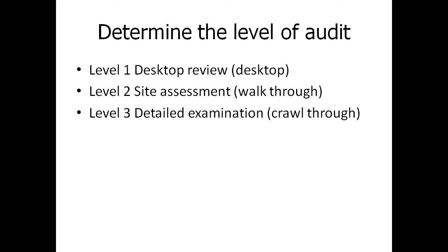So that may require site investigation on top of roofs, taking photos, and reporting back again in the same sort of elemental format. The level 3 is detailed examination. Now, to do detailed examination on a portfolio of buildings, or even on one particular large building, might not be feasible. So with detail, it might mean totally stripping down some of the plant and equipment, very time consuming, and sometimes putting some of that plant and equipment out of operation for a short amount of time.